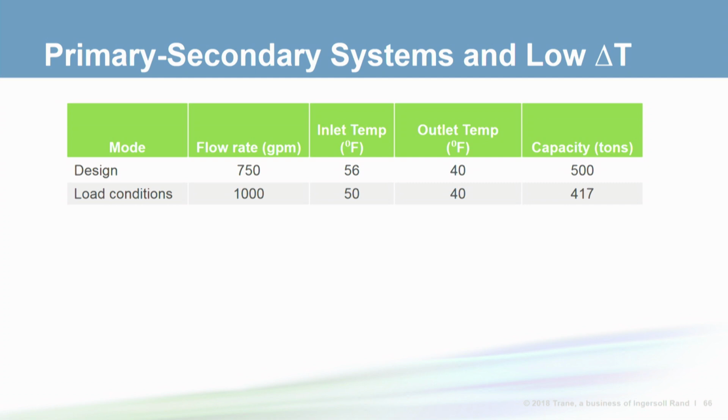the load. If only one chiller and its pump is operating, there is 750 GPM of flow through the chiller. Since the return water temperature is only 50 degrees, the chiller can only deliver 313 tons. So the second chiller and its pump must be added to help satisfy the remaining flow and capacity required. While the flow issues are now overcome, there are a number of pieces of bad news.